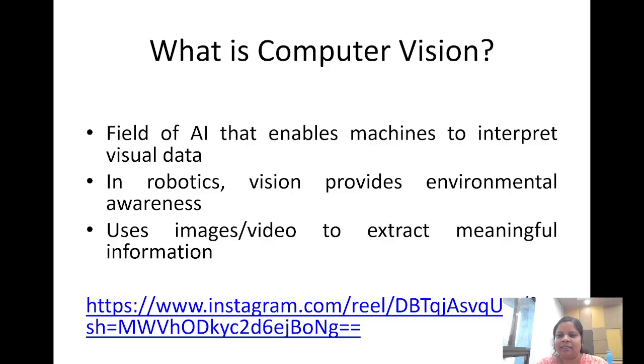Now we have eyes, right? The robots don't have eyes, so they use a camera for the same. Now, how do you interpret those camera images? If you use a stereo camera, you can estimate the depth, but if you're just using a monocular camera, you'll only be able to say that this is the 2D image of the scene, but you never know what the depth of the image is.